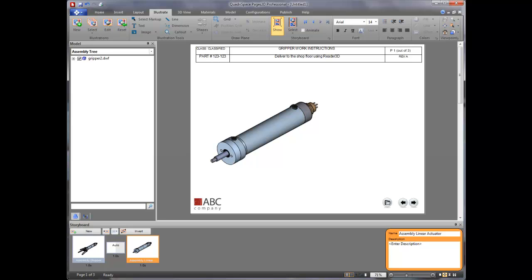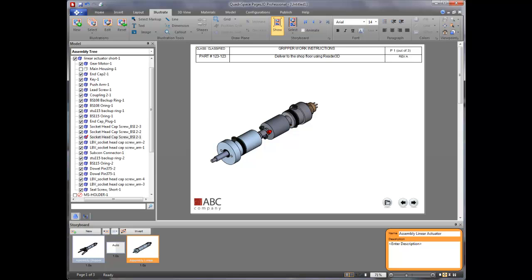And then we're going to move on and do a final last configuration using this motor. I'm going to use a little different method for creating it. As I said earlier, configurations can be any arbitrary set of parts. It was convenient for us that the second configuration, the linear actuator here, was a subassembly. It made it very convenient for us to set that configuration up.